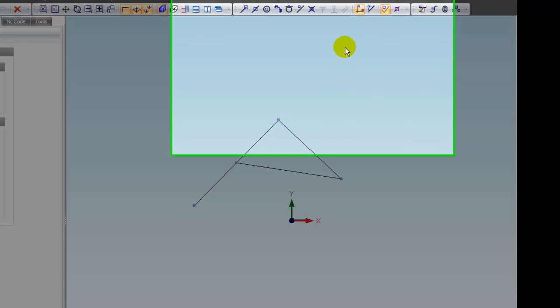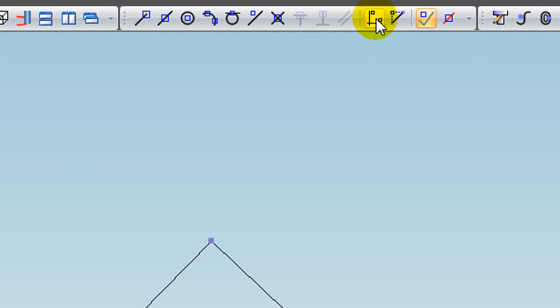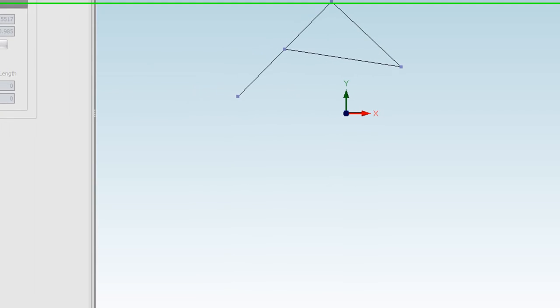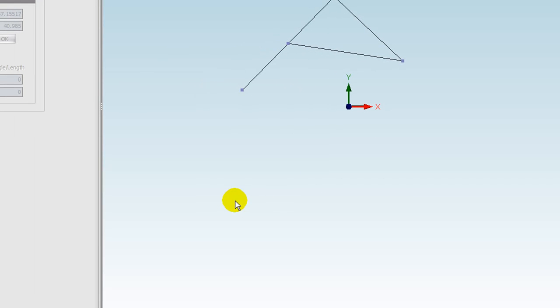Before I move on, I want to show you this feature here, snap orthogonal, which is active at the moment. If I put the start point of the line down there, this enables us to draw horizontal and vertical lines. It only works when we're trying to get the end point of a line. If I move near to horizontal, you see we get a blue snap marker to indicate where the line endpoint will be if I left click, and the cursor has also changed to indicate that. We can do this at all of 0, 90, 270 and 180 degrees.